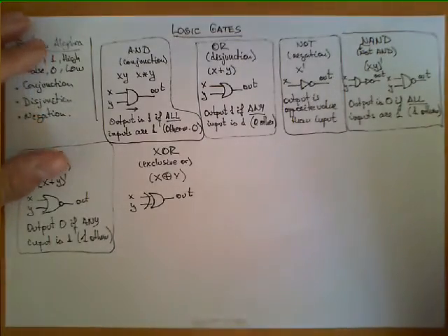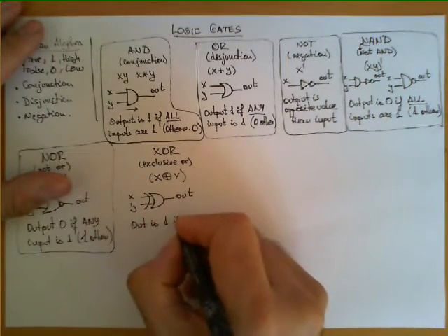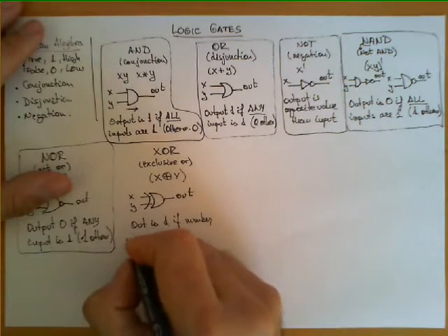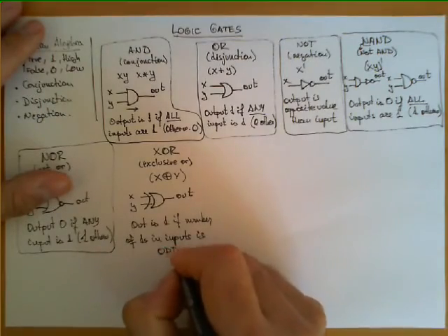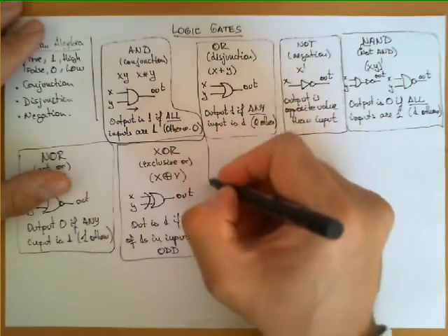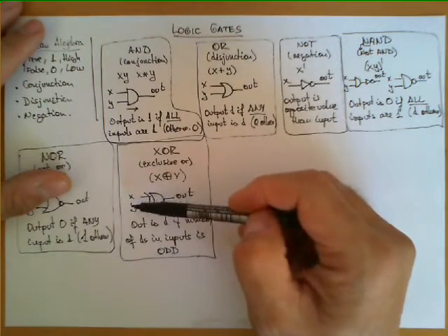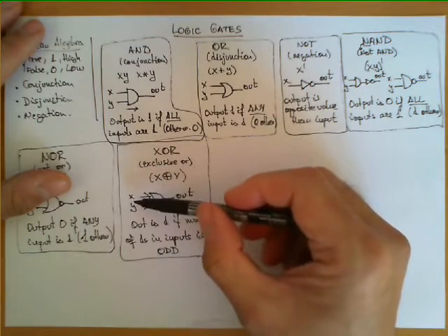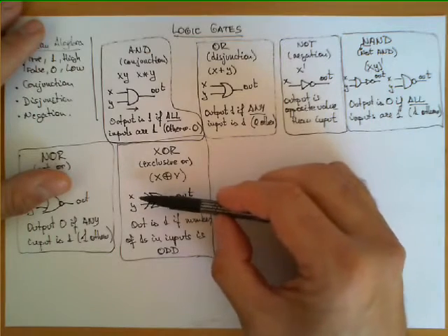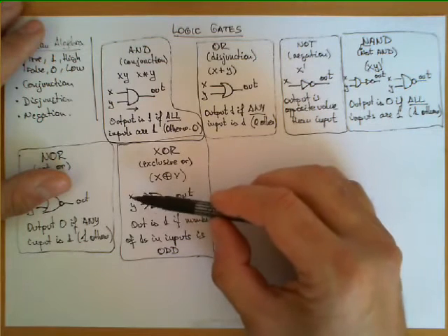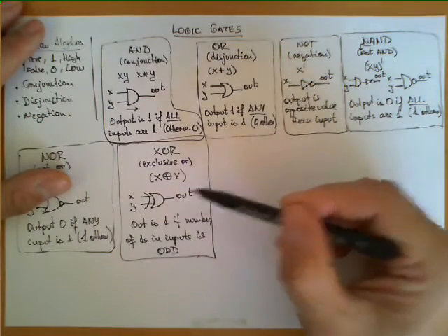Now this is a logic gate that has a very interesting rule. The rule to compute the output of this gate is the following: the output is going to be 1 if the number of ones in the inputs is an odd number. For this gate it is kind of trivial, since we only have two inputs: the possibilities are none of them being 1, which would be zero ones, one of them being 1, or both of them being 1. So this gate is going to produce a 1 when we have the 1-0 combination or the 0-1 combination at the input. For the other two remaining combinations, 0-0 and 1-1, since both have an even number of ones, one has 0 ones, the other has 2 ones, this output will produce a 0.